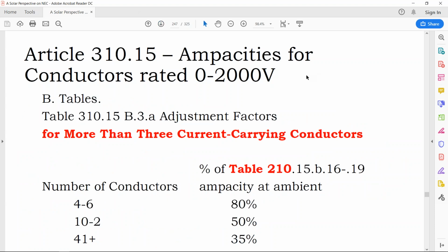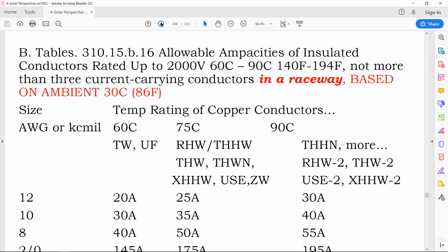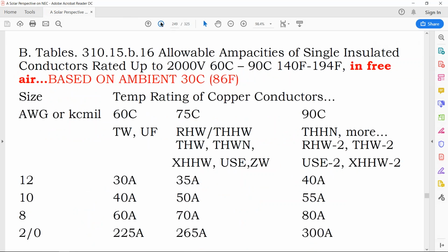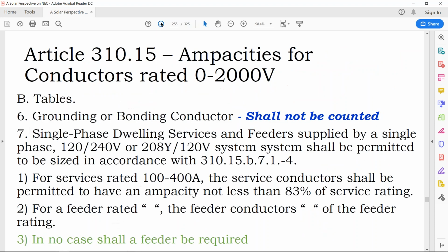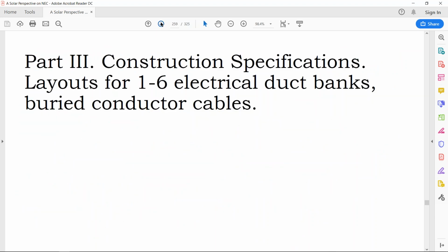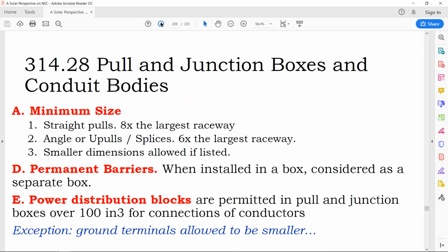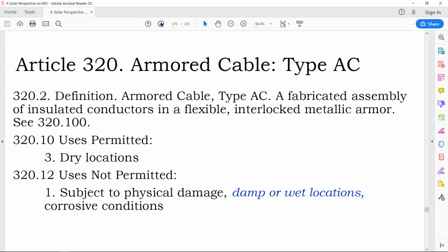Then there's an additional derate factor for how many conductors are inside that conduit, because these conductors generate heat. And there's certain cables that are rated for higher temperature ratings. So I'm just going to kind of skip forward to the solar section and battery section. And if you have questions about other stuff in the content that we're skipping over,